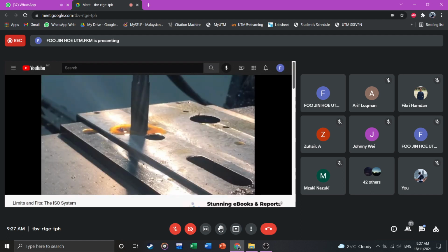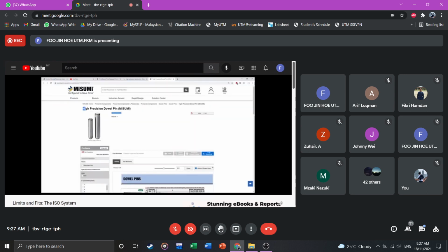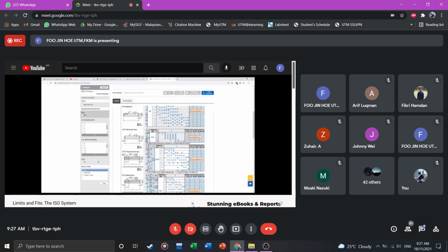Because there will be other smaller pins, and your reamer will sometimes cut larger holes, you may also find yourself cutting the largest possible hole for the smallest possible pin. The extra space on top of the allowance is called the clearance. If the clearance is too large, the fit might not work. The only way to change the clearance without changing the allowance is to tighten up your tolerance zones, either by changing your manufacturing methods or buying tighter tolerance pins.